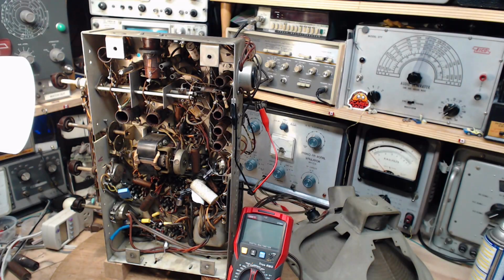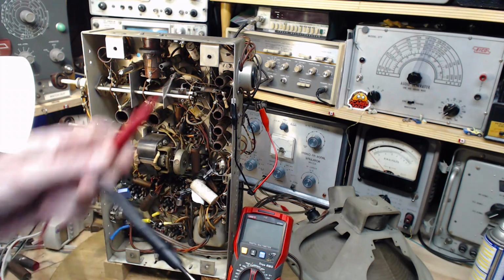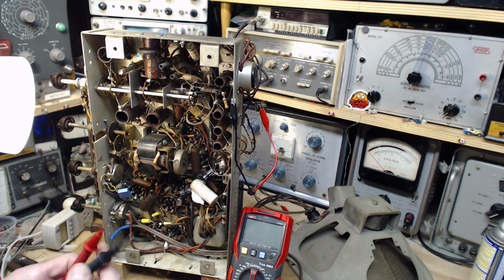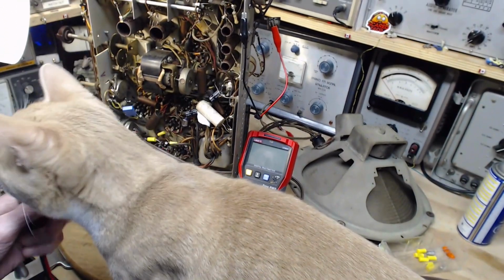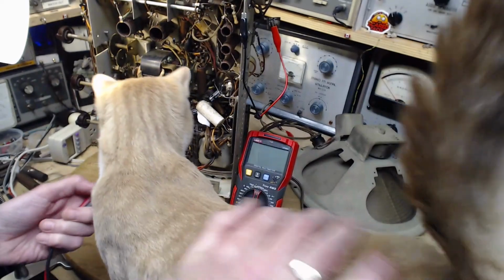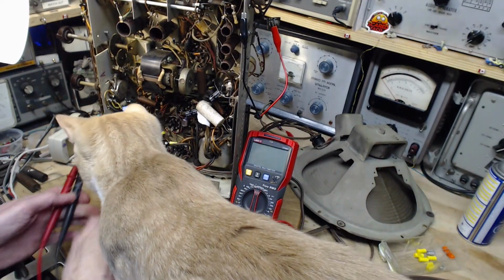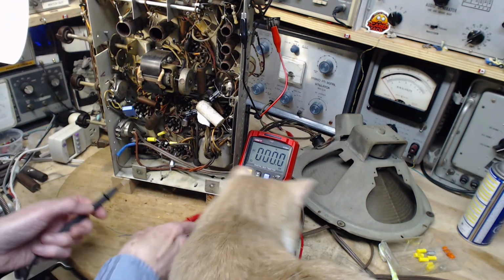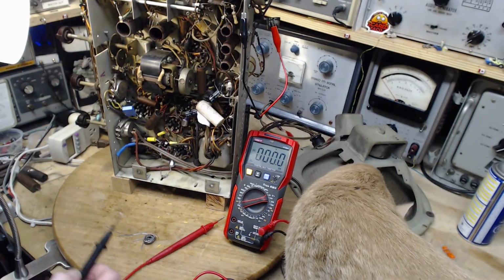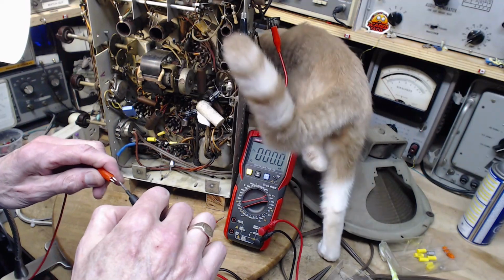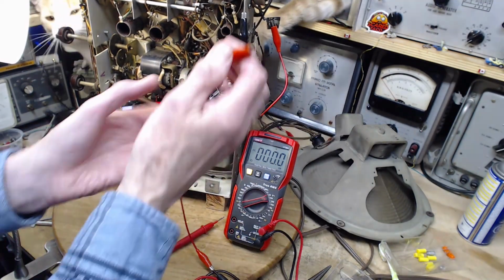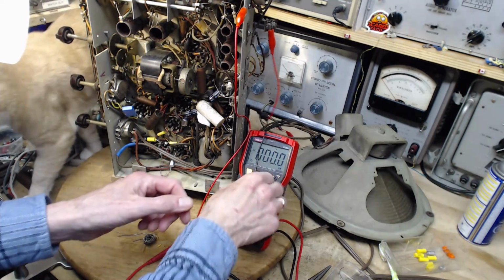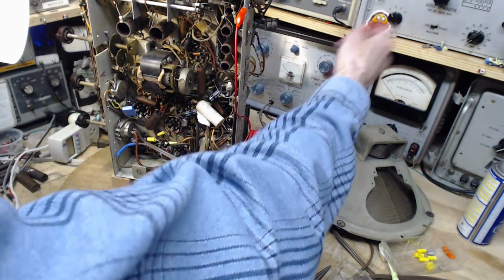Kind of hate to do it, but I think we need to read the voltage across the capacitor while the radio is operating, just to see if I didn't put a 200 capacitor into a 300 volt spot. Gosh, I can't get away with anything here anymore. What are you doing here now? Okay, so we're going to be reading a fairly high voltage. I'm going to do it right across the, well, the capacitor goes to the chassis, so that's not a problem. Clip lead, one lead to the chassis here. Oops. And that doesn't really matter either. I can take that off.